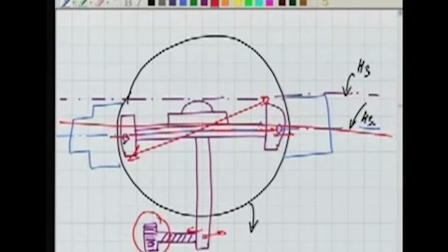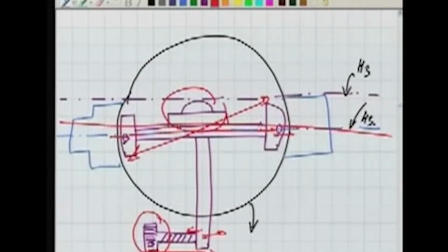But is the altitude bubble in center? No, because I have used this screw, so this altitude bubble has gone out of center now. It is not in center. I have rotated this in order to make the reading 0, 0. So I need to make this altitude bubble in center now. So what I do, in the instrument, again we have got the capstan screws. If you can see here, these are the capstan screws in the instrument, and using these capstan screws, I can move this bubble either up or down, and I bring it to the center.